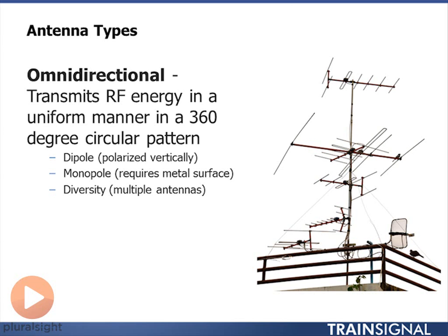So an omnidirectional antenna has a gain relative to the isotropic antenna, but is forming that donut type shape, and that's what you want if you're deploying an access point covering something like an office area where you want to cover the whole floor area and you want a 360-degree circular pattern, but you don't really want to be radiating down to the floor below or the floor above you. So you create this omnidirectional, donut type shape, and it gives you a gain relative to the isotropic antenna.